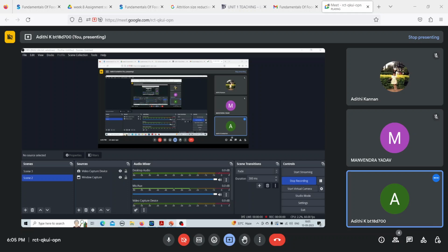So the equivalent surface diameter is the diameter of a sphere having the same surface area as that of the particle. So here we know that the particle is cylindrical in shape. So the surface area of the cylinder can be given as 2 pi r into r plus h. So we know the length is given as 12 millimeters, which is h here. Diameter is 8 millimeters, so radius is 4 millimeters. The surface area of the cylinder can be given as 2 pi into 4 plus 12. So this gives me the surface area, which is 401.92 millimeter square.